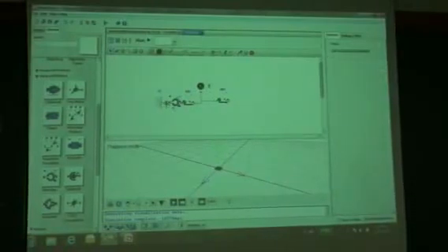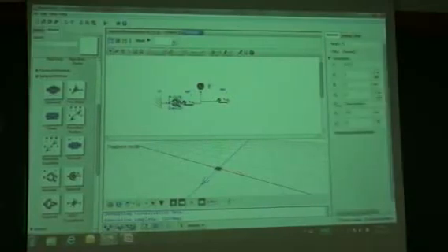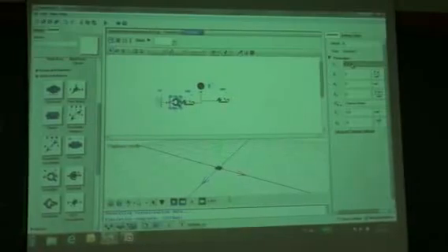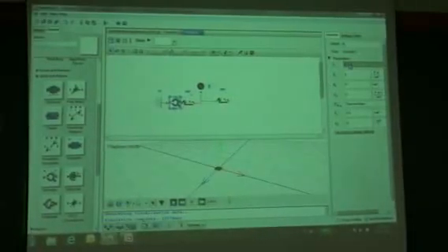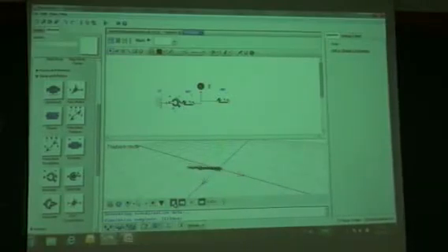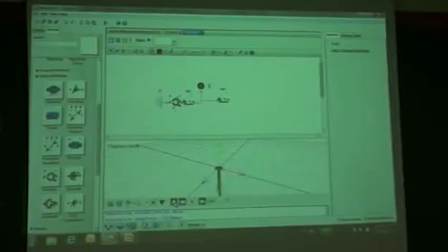I'm going to put in here a revolute joint. This revolute joint is just a hinge. The axis is going to be the z-axis, so into the screen. Now I'm going to run this. Anybody like to guess? Simple pendulum, because we actually have gravity, so it's just pulling on gravity.